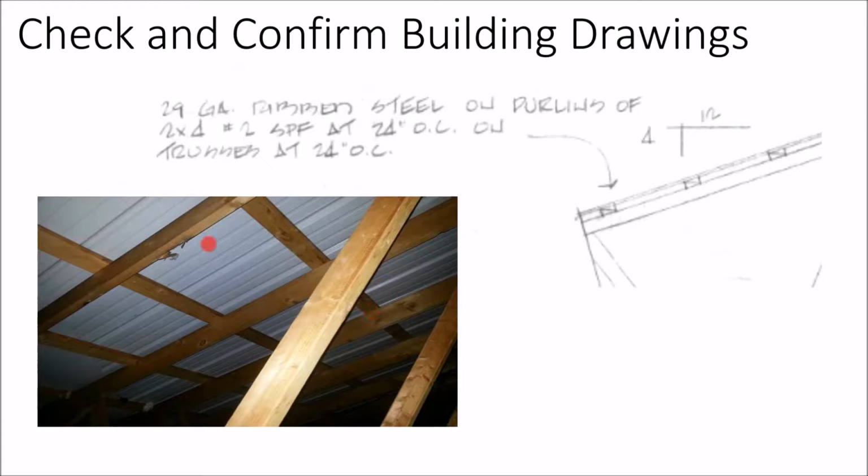I'd say a common attic picture is this, just to confirm what's going into the attic, but you may also want to take a picture of what the truss shape looks like. But in particular, also hurricane clips: whether the truss is secured to the building wall through hurricane clips or not.